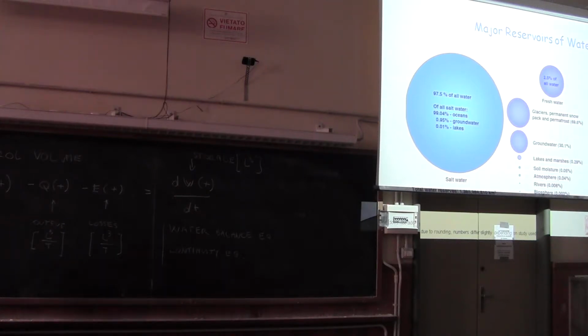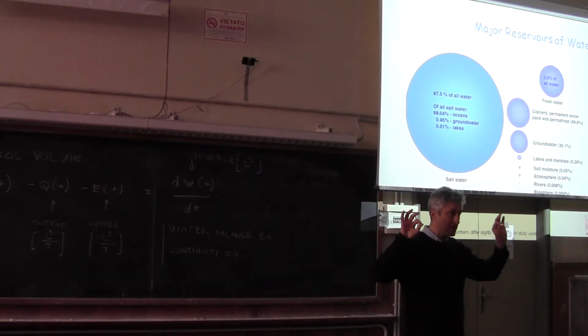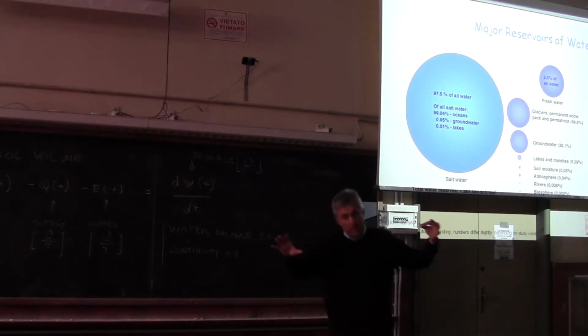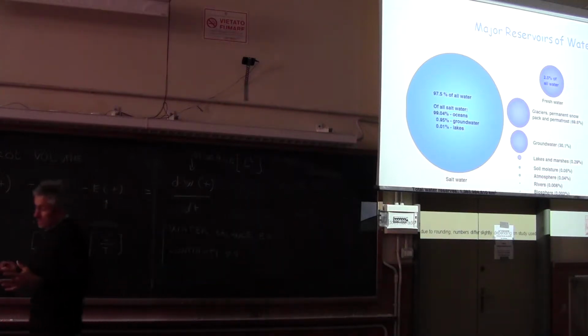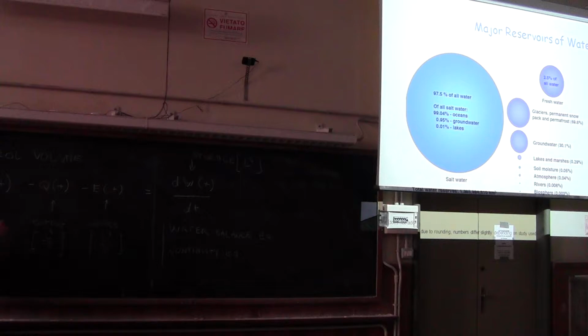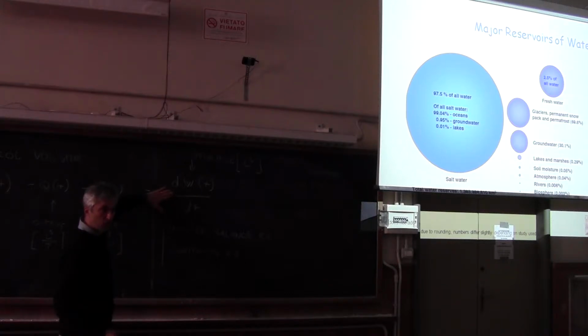What is this equation from a physical point of view? It is, as I already mentioned, a mass balance equation, which refers to the mass of water. Basically, this is a balance of volumes, because there is a flux of volume entering, a flux of volume exiting from the control volume, a flux of losses, and which is equated to a change in volume of water storage.